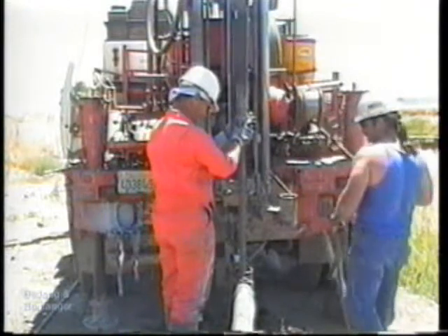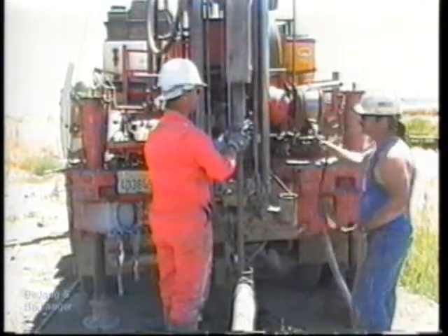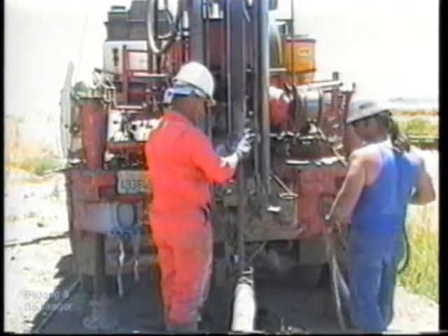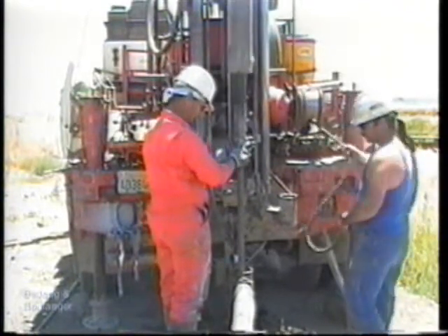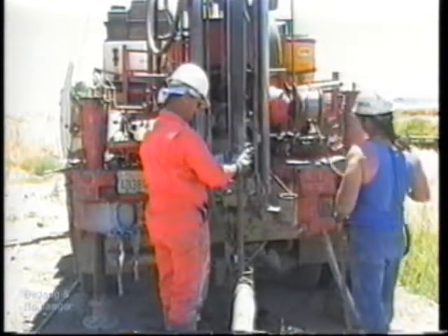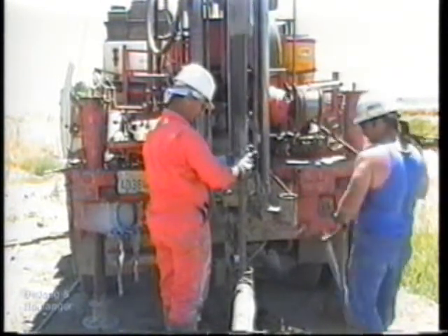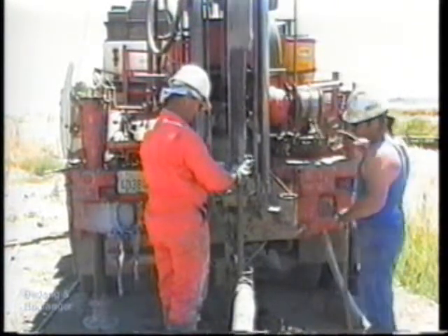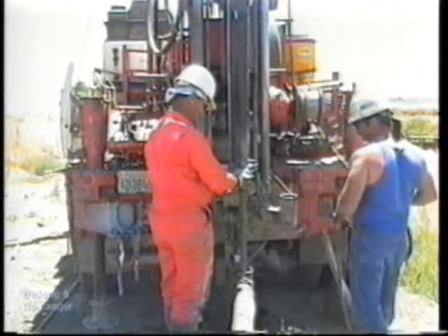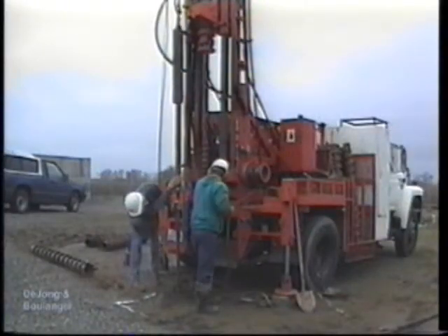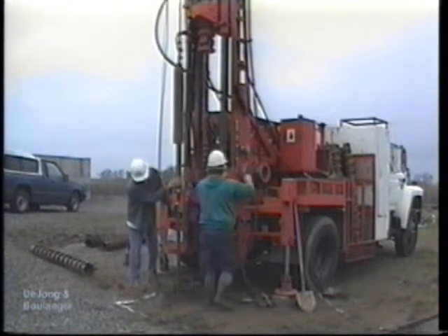Since the N values are inversely proportional to the energy delivered, energy ratios of 30% to 95% can cause N values to vary by a factor of 3 or more. Mechanical trip hammers provide a more repeatable energy input, while the energy from drop hammers can vary as the driller becomes physically tired and slowly reduces the hammer drop height, number of blows per minute, and other variables. Thus, it is highly recommended that the energy delivered by a particular drill rig be calibrated on important projects.